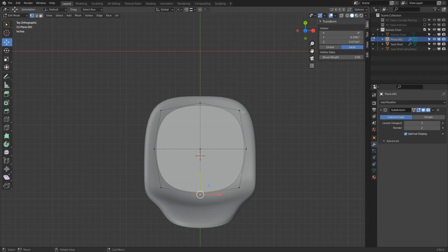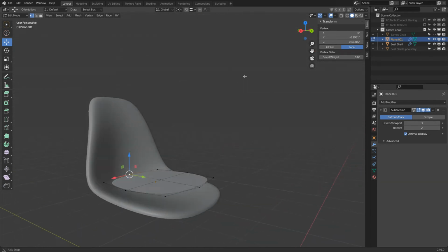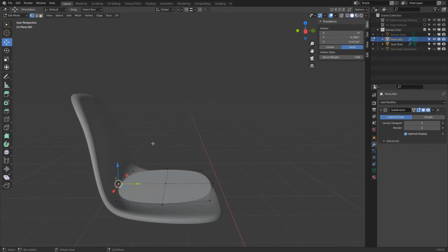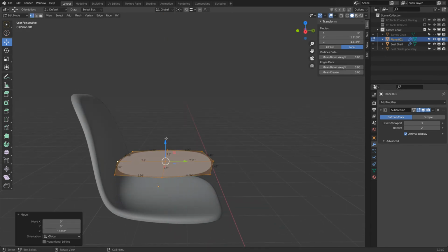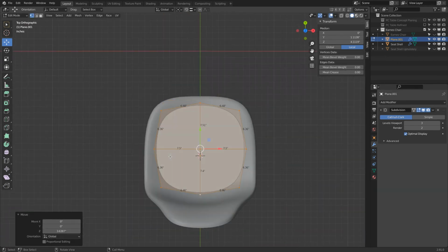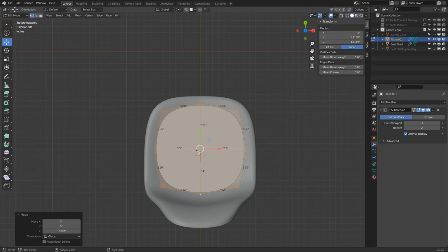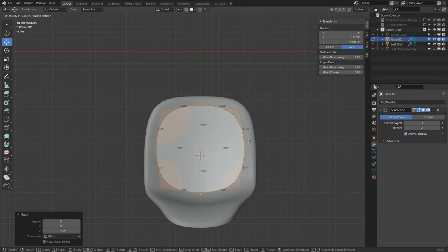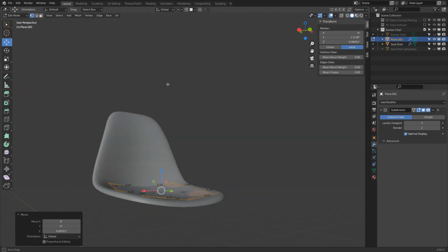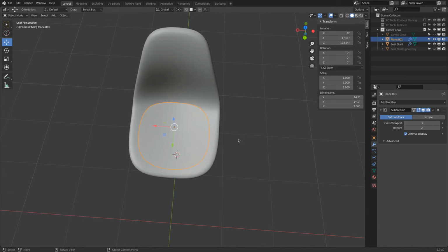Yeah. Cool. So I moved this up a little bit on purpose because I want to show you something. So we go to the top view, face, and project individual elements. Very good. So this is the Z-axis. Now I press G and Z and hold the control key and click. And you see, flop, it pushed it onto that surface.